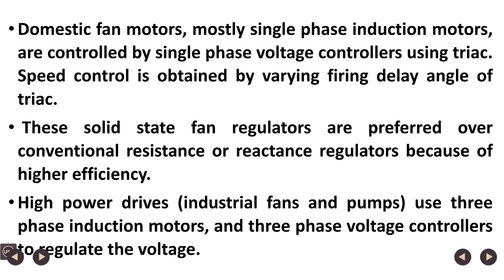The solid state fan regulators are preferred over conventional resistance or reactance regulators because of higher efficiency. Conventional fan regulators use a voltage control technique using resistance or reactance, so that increases the loss and efficiency is poor. In this case, there is no loss. And high power drives, for example industrial fans and industrial pumps, use 3 phase induction motors and 3 phase voltage controllers to regulate or control the voltage applied to the fan or pump.